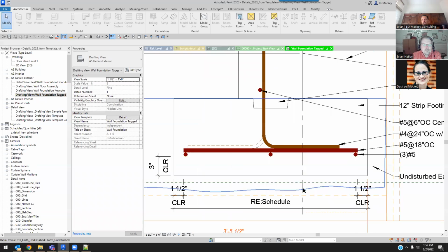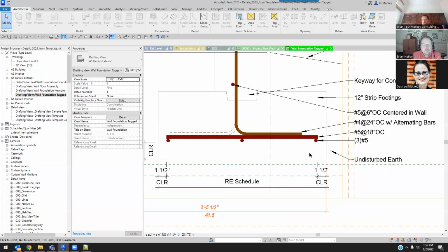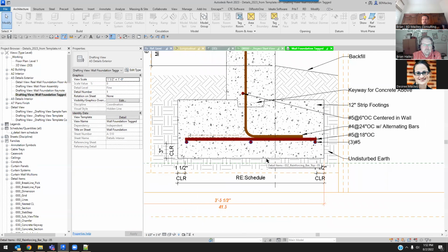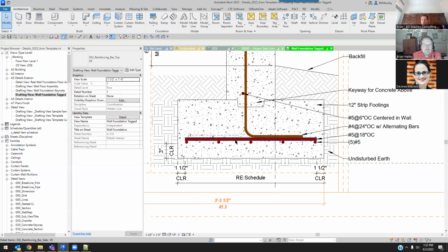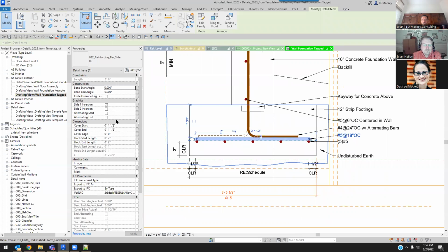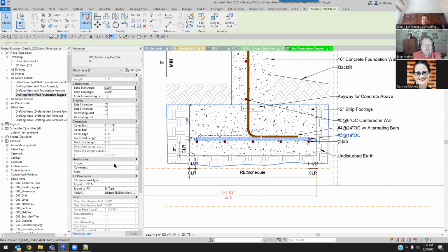But for me, when I start looking at this, you can start to see these are all Revit native components, and even something like this. If I come in and grab this rebar, like, oh, I didn't want 3 down here, I wanted 5. If I change the value here, the tag updates. I got 5 number 5s, right? Even this one here to the side, you don't really see it, but this is holding the information of what is the spacing on here.